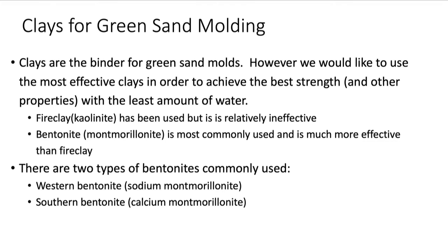And so clays are basically the binder that we have in green sand. So we want to use the right kind of clay. Now there's all kinds of different clays. If you've ever played with pottery or whatever, usually you're using something like a fire clay, kaolinite, which can be used, but it's not very effective. It takes a lot of clay, and it's not very strong.